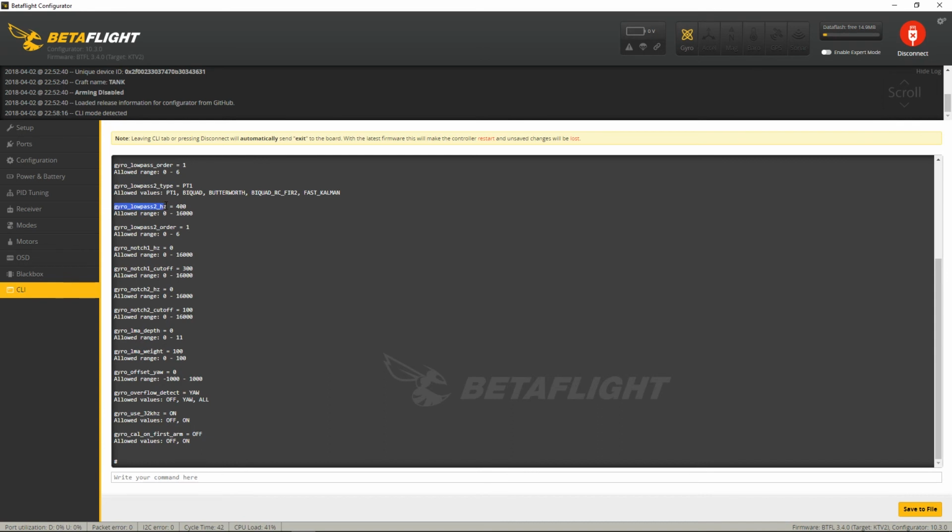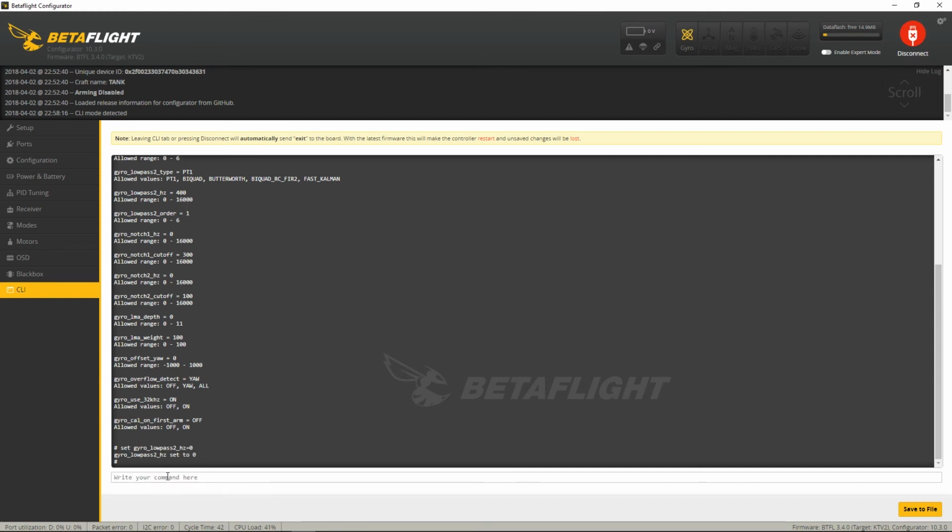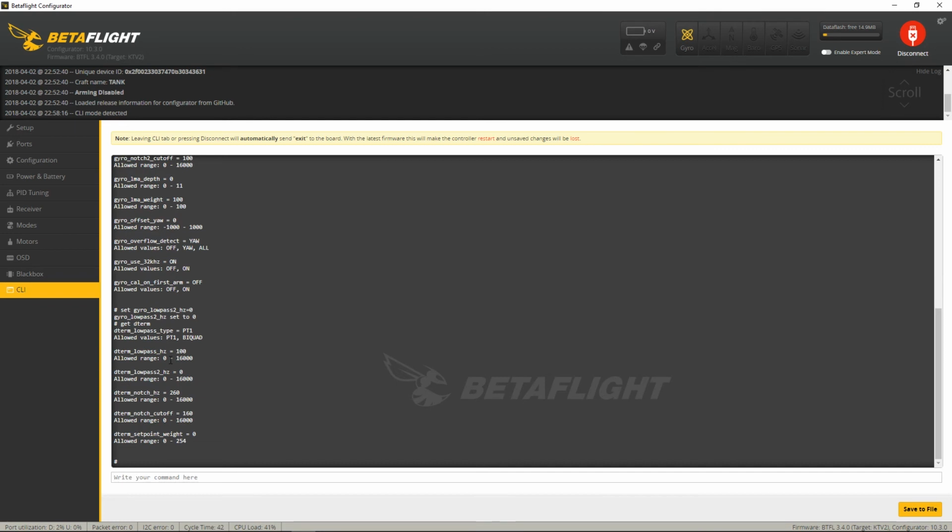We turn off the gyro low pass 2, and we apply the D-term low pass 2 to 650.